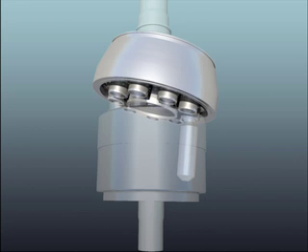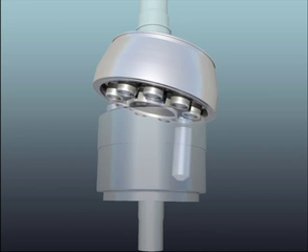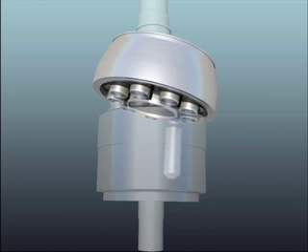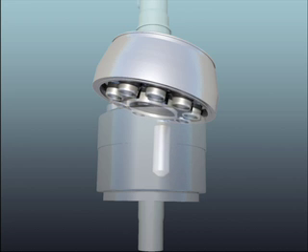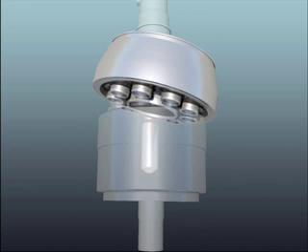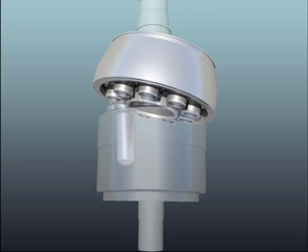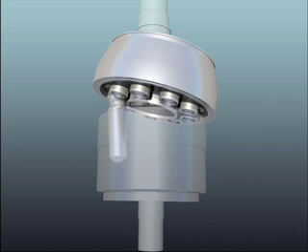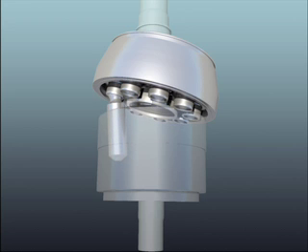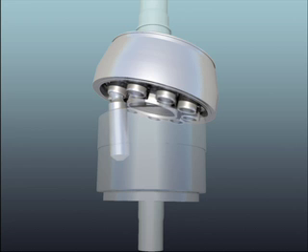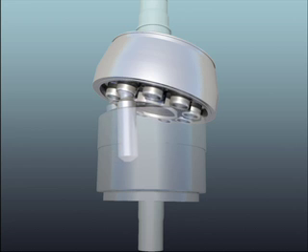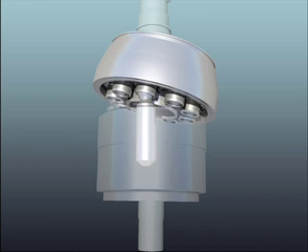As the piston continues to precess about the cylinder block axis, it moves away from the valve plate, thereby increasing the volume of the trapped chamber. As this occurs, fluid enters the chamber from the pump's inlet to fill the void. This process continues until the piston reaches the bottom of the reciprocation cycle, commonly referred to as bottom dead center or BDC. At BDC, the connection between the pumping chamber and inlet port is closed. Shortly thereafter, the chamber becomes open to the discharge port again and the pumping cycle starts over.